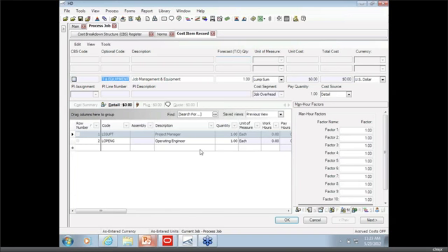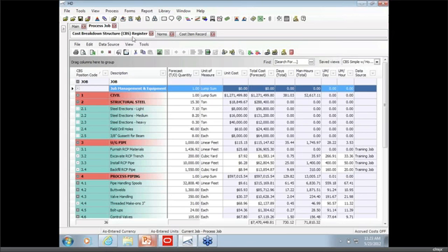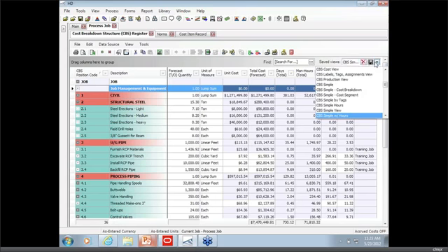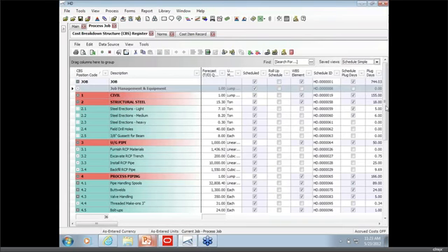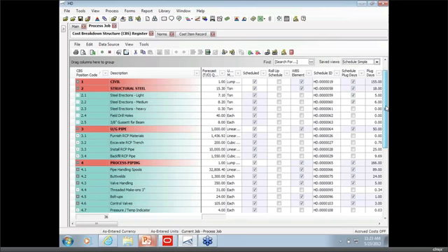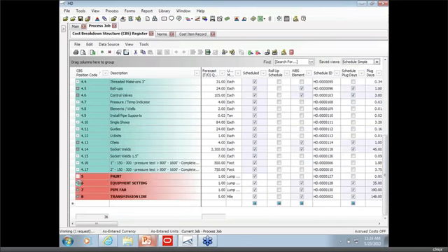What I want to do is have the cost for these two resources driven by the schedule. So depending on how long my project's going to be, I want that duration to generate the cost of both the project manager and operating engineer. In order to do that, we need to rely on our integrations with scheduling applications like Primavera and Microsoft Project. So real quickly, I'm just going to switch my view here to my scheduling view. And I've already scheduled this cost breakdown structure. So a very similar structure will reside on Primavera when we switch to it.